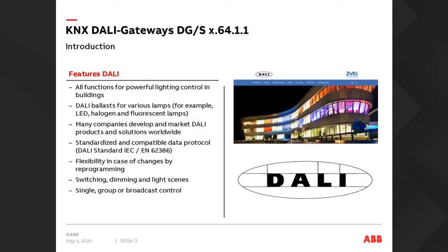They must have a standard set of connections. It enables us, as manufacturers of DALI control devices, to be certain that whatever gateways we release into the market will control DALI 2 certified devices. I can't guarantee DALI 1, because some of the manufacturers are still doing funny things, but we can guarantee that we can control all DALI 2 devices because our gateways are all certified to DALI 2.